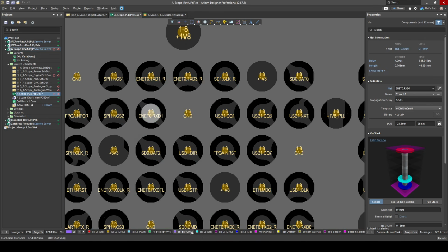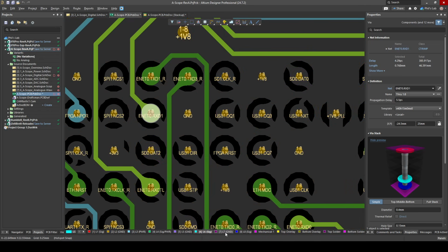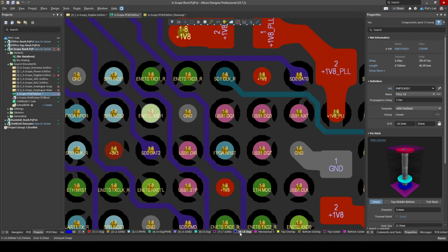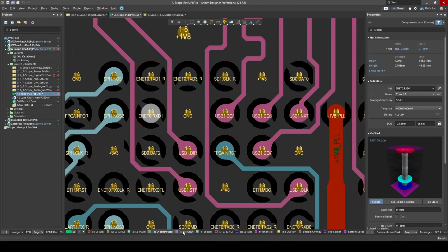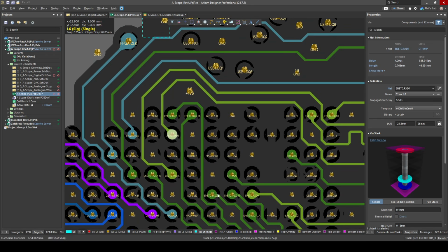I have ground on layer 5 and ground on layer 7, but also rather than dropping from layer 1, for example, to layer 3, I drop from 1 to 6 because with my via, I only have a stub on layer 7 and layer 8. So a comparatively rather short stub compared to routing from layer 1 to layer 3, which leaves a much longer stub through the remaining layers. So I've tried to fan out as best I can.